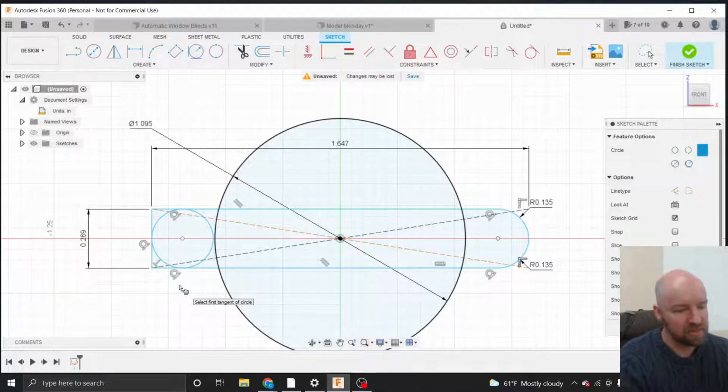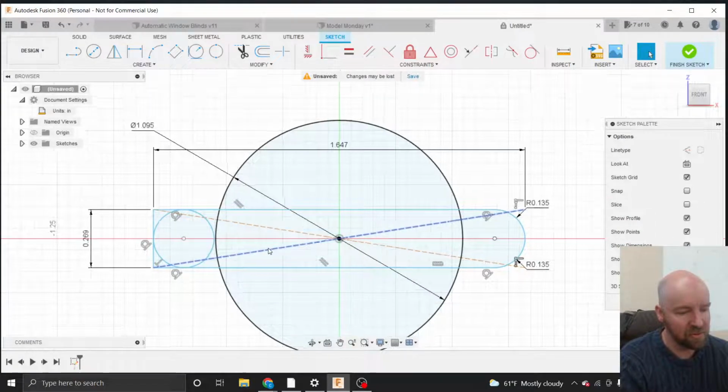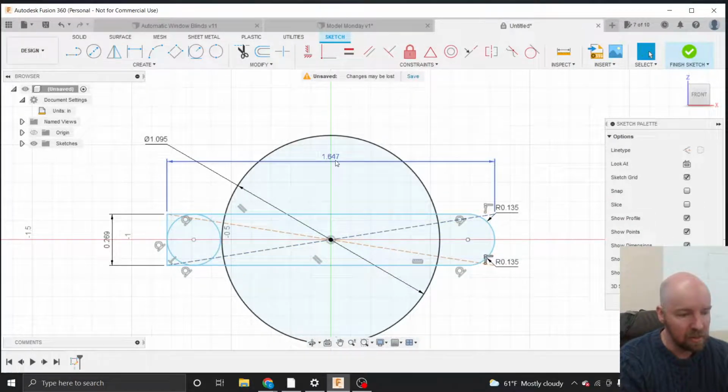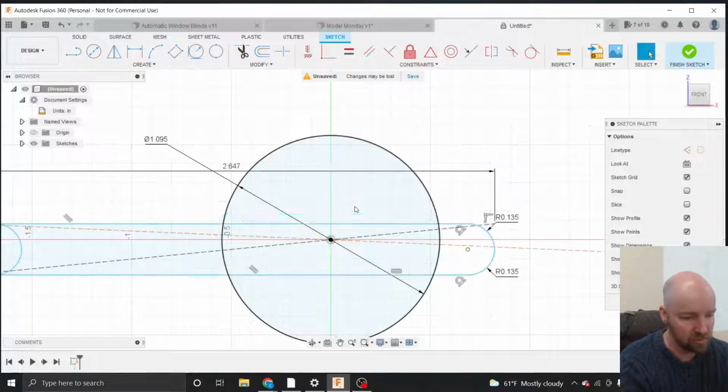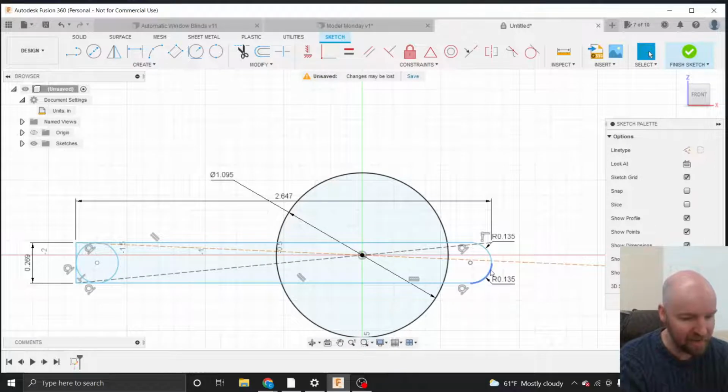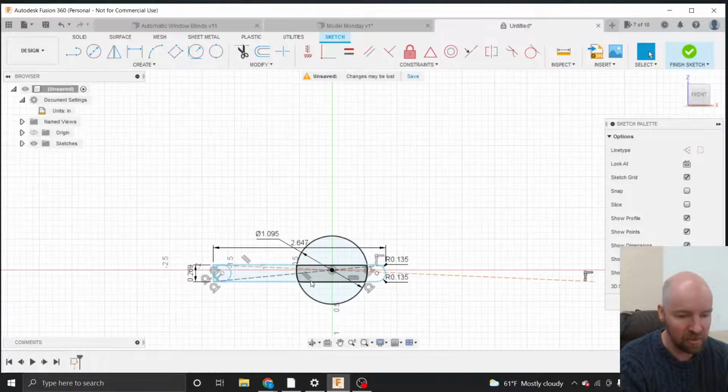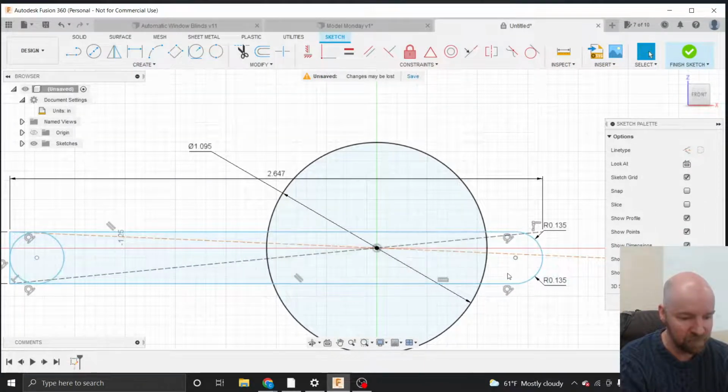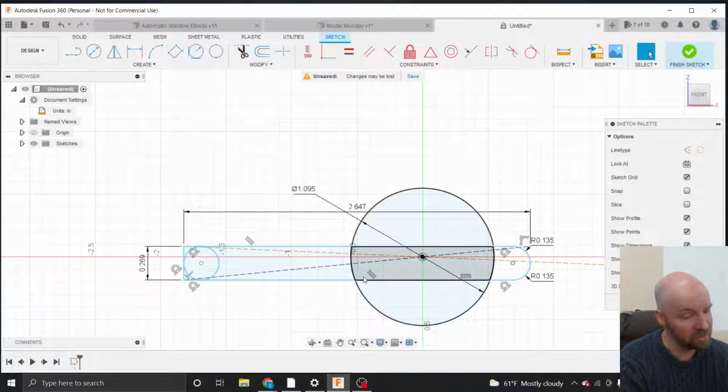I am curious now. Whenever I find that there is more than one way to do something, I choose the one that is going to be the most easily changeable later. I bet this fillet option, if I start changing this measurement, is going to swear at me. Yeah. When I made this fillet, it somehow broke my center rectangle, so now it's no longer centered.